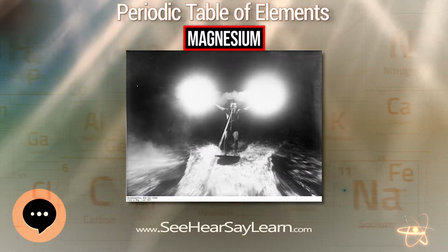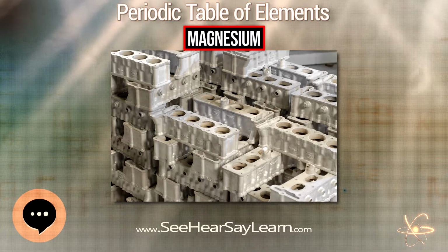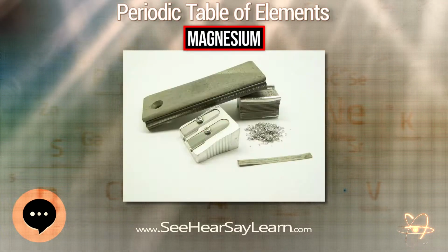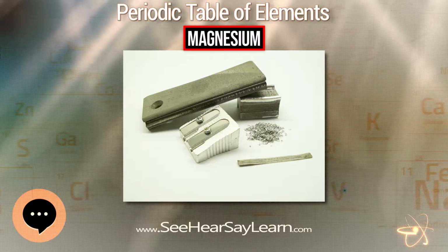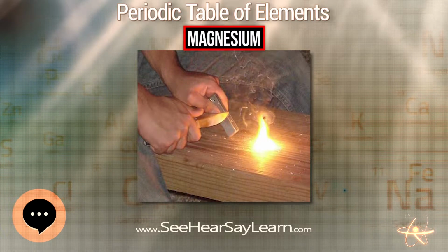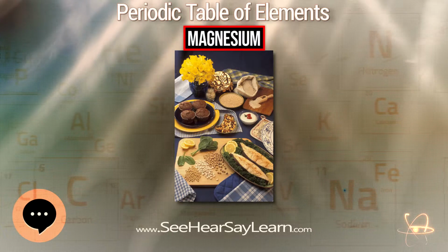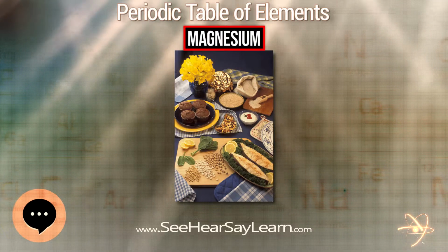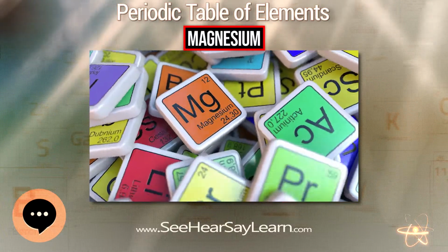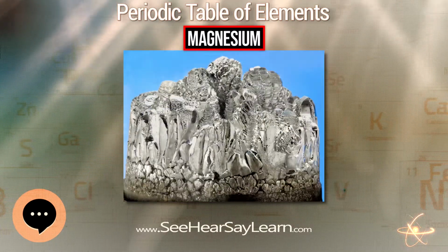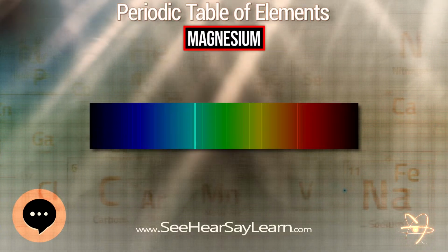As of 2013, magnesium alloy consumption was less than 1 million tons per year, compared with 50 million tons of aluminum alloys. Its use has been historically limited by its tendency to corrode, creep at high temperatures, and combust. The presence of iron, nickel, copper, and cobalt strongly activates corrosion. Greater than a very small percentage, these metals precipitate as intermetallic compounds, and the precipitate locales function as active cathodic sites that reduce water, causing the loss of magnesium.